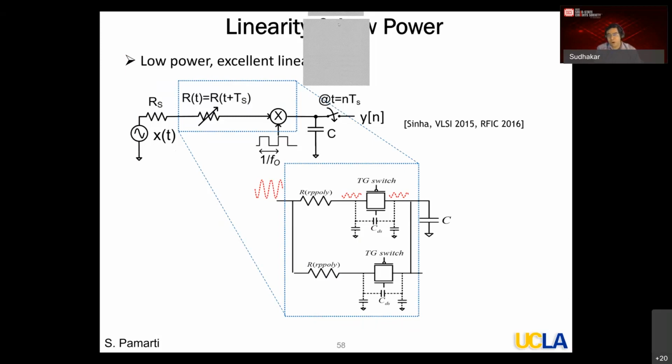But if you go to a millimeter wave kind of situation, then the bandwidths over there are much wider, so I don't think it will be applicable there, at least as of today. Perhaps there is some other way of doing so. But the LO frequency itself can be pushed higher independently. Having said that, if I have these resistors and switches all showing up in front, there will be some capacitance from those switches and so on.